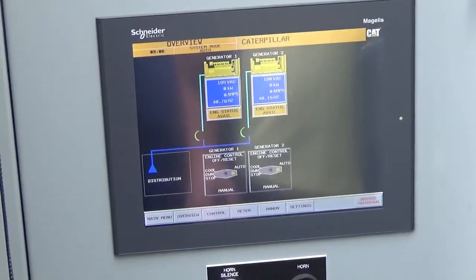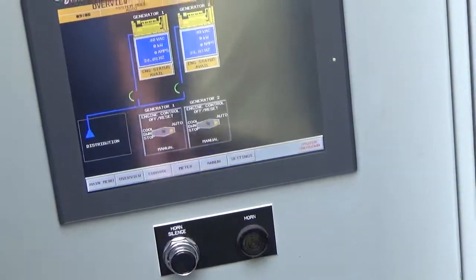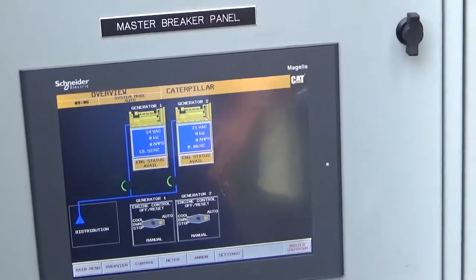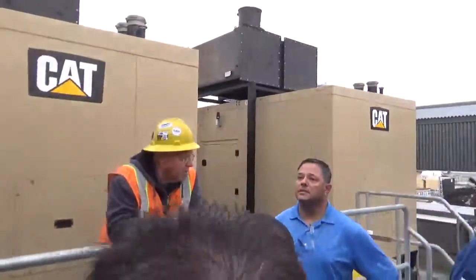Yeah, like I said, it's nothing. Okay. Until we start loading. Well, I will show you. You have to control that, so you can turn the load off, let it run for a couple minutes, and then shut it off, and then we're going to a 2-minute cooldown. You only need a high cooldown when the hospital load is going heavy.